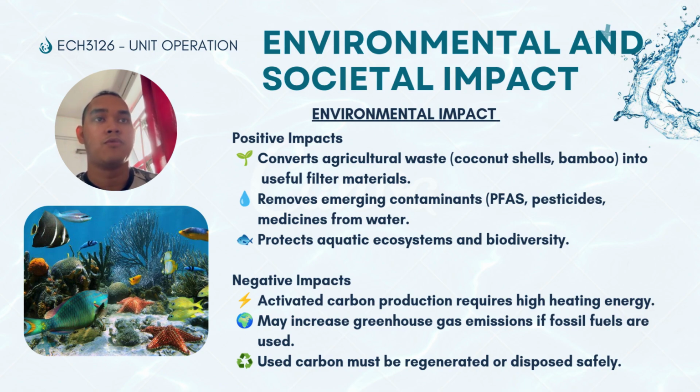Activated carbon also improves water quality by removing contaminants such as PFAS, pesticides, and pharmaceutical residues, helping to protect aquatic ecosystems. However, there are challenges, such as producing activated carbon requires high temperatures and large amounts of energy, which may increase greenhouse gas emissions if fossil fuels are used. In addition, used carbon must be regenerated or disposed of properly to avoid creating secondary pollution. Overall, activated carbon can support environmental sustainability, but only when energy use and waste management are carefully controlled.